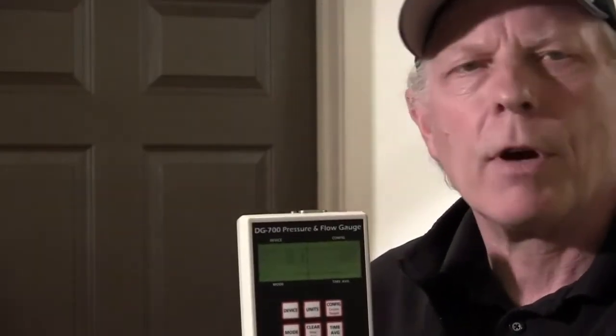Okay, we're on line 3 under combustion appliance zone testing. This is where they ask the candidate to measure the baseline differential. I'm going to go ahead and turn on the manometer and turn on the light here. Today there's no wind, and it's not a very big temperature difference between inside and outside, so we don't have much to affect the baseline. Right now I'm reading about -0.2.